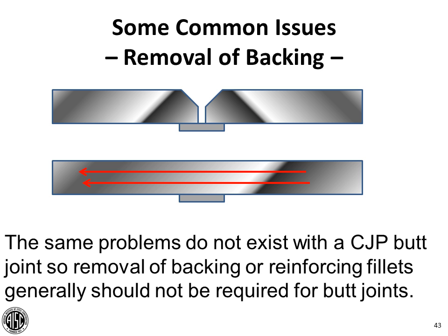And engineers are free to require, demand critical welds or removal of backing or contouring in other locations beyond what's in the seismic provisions. Again, I would recommend, unless you have some very good reason to do so, that you should probably just stick with what the requirements are as written in the provisions. But if you decide you need to add these additional requirements beyond what's in the specification or what's in the provisions, I would say go the extra mile to try to make sure that those are very clear